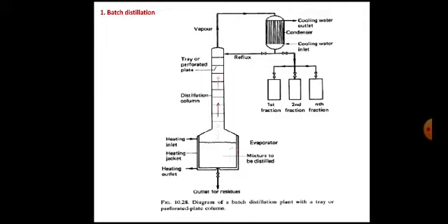The vapors rise through the pores present in the perforated plates. These vapors will further enter into the next chamber, that is the condenser. As the condenser has a dropped temperature, these vapors get converted into liquid form. Then this liquid is allowed to re-enter into the distillation column.